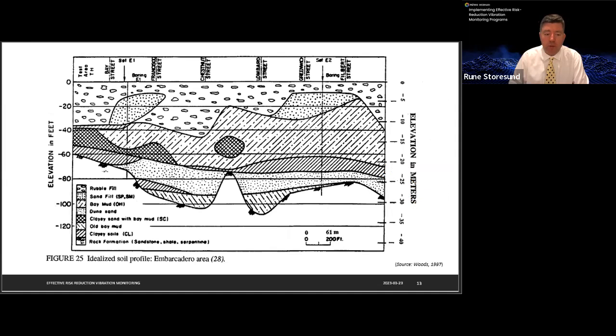Soil conditions can be variable beneath the construction work area. There can be zones of soil materials that may be susceptible to densification, which could, depending on their location relative to the overlying structures, result in a structural impact to those overlying structures. The variable soil conditions may also have an impact on the attenuation and propagation of the construction-induced ground vibrations. Most geotechnical subsurface exploration campaigns don't directly assess the vulnerability of subsurface soils to construction-induced ground vibrations.